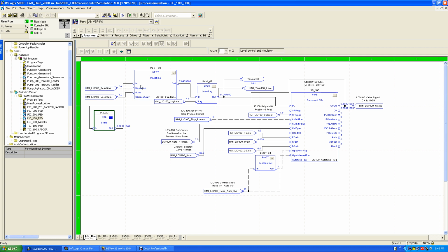And you bring that into your dead time. And here we have a dead time tag that says how many seconds of dead time. And that dead time will actually set, and we also have a gain of how much gain, a process gain. This gives us a process gain. And I set this between like 0.75 and 1. You might want to get down to 0.5.